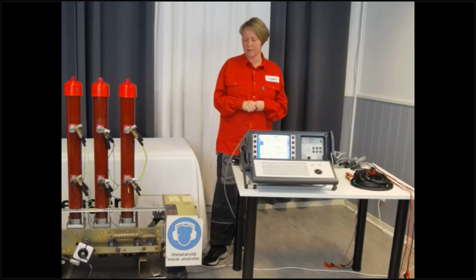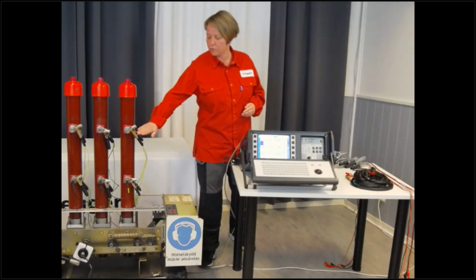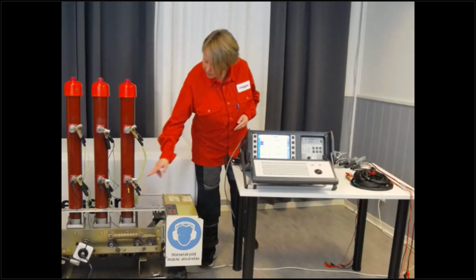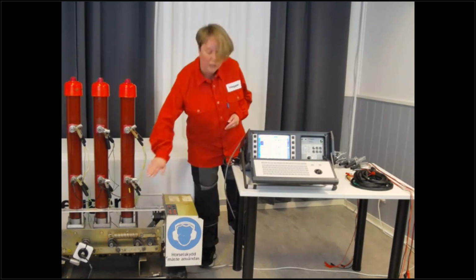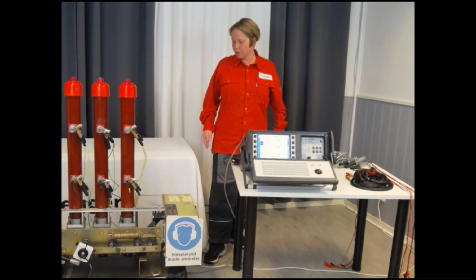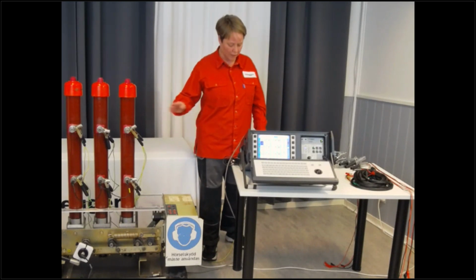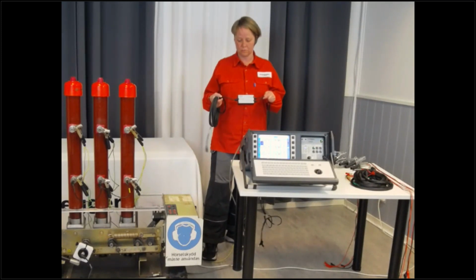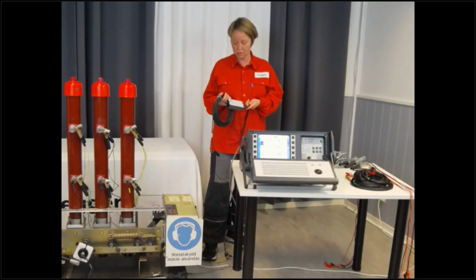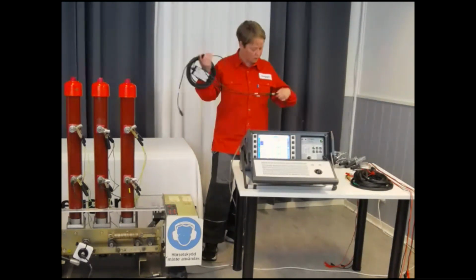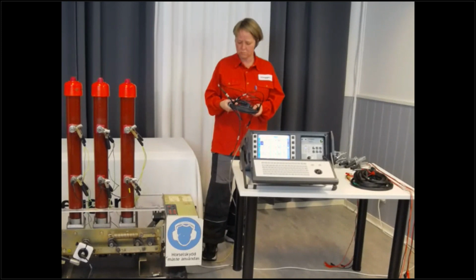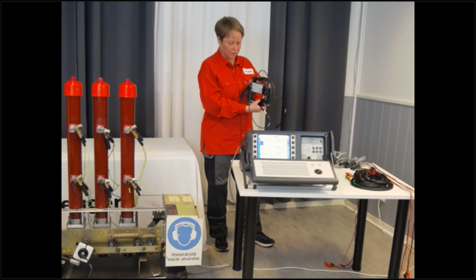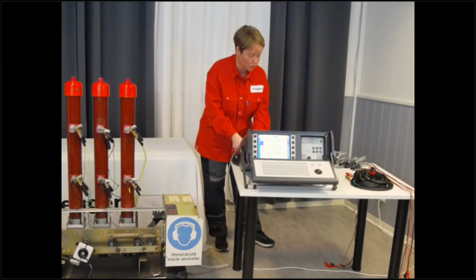I have prepared my setup here. I have grounded all phases on both sides. I even kept the ground. It doesn't really matter, actually. I can have one side common like this. I'm going to do timing with dual ground, and then I need to use this type of cable instead of a normal timing cable. So it has a little box. I think I weighed this equipment once, and it was 900 grams, and the normal cable is 600 grams. So it's not much heavier and not very troublesome to connect.